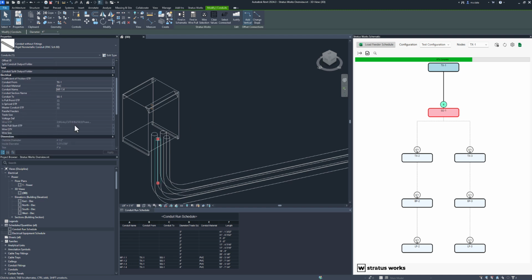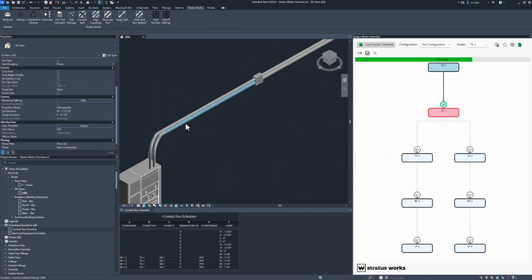You can also see that those connections have been reconciled in our Schematic Viewer. They show not only that these are connected, but the conduit lengths and the circuit lengths, which derives a length from the conduit as well as a wire makeup value at each connection point. This also tells the overall change in bend angle as we propagate through those runs. Now we are going to go fill in the rest of this system.